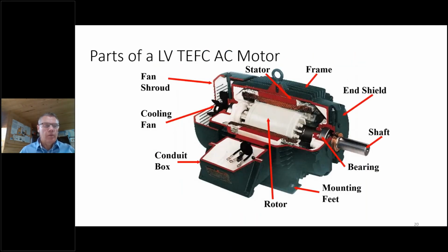Just moving along fairly quickly here, just a little breakdown of what you might see in a typical low voltage motor. This wouldn't be every single motor you'll come across in the field, but this is a cutaway of a typical IEEE 841 motor, which is the workhorse of the industry. It has a lot more enhanced features for protection.